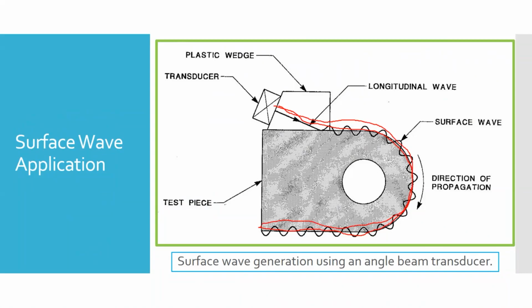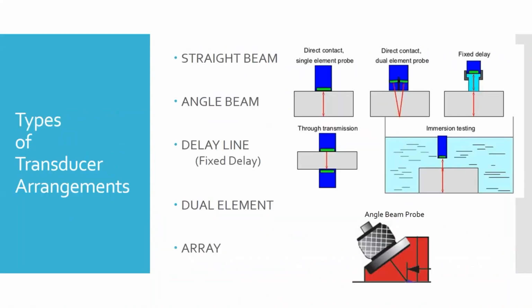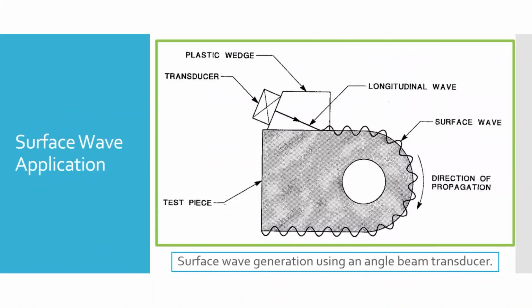What that allows us to do is, if you imagine that we have a break or a crack somewhere along the part, right, now our wave would reflect off of that crack or that break, and so it wouldn't take as long. We would get a return echo sooner than it would be if it was going all the way to that back wall at the bottom left corner there. And so it can be used for that.